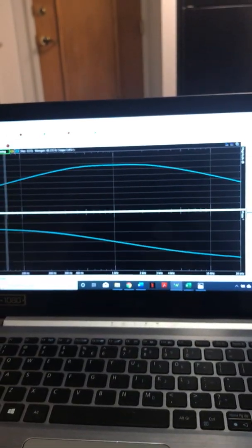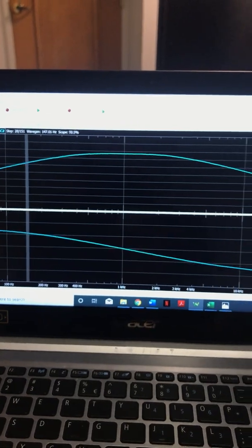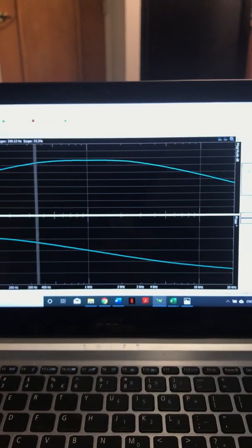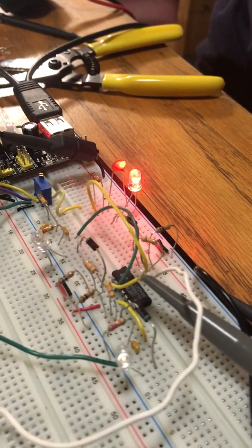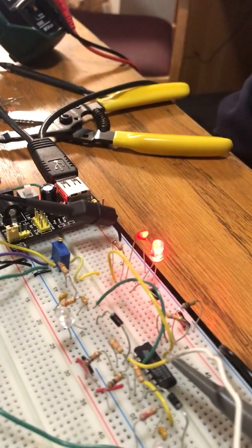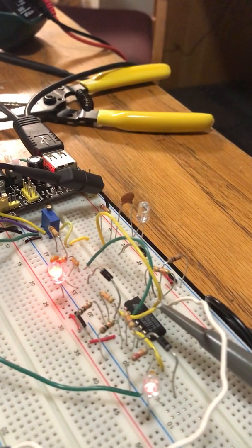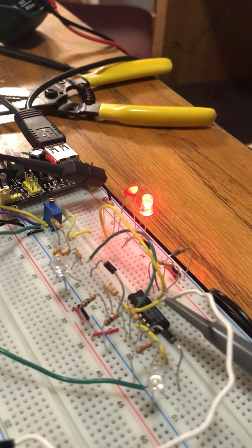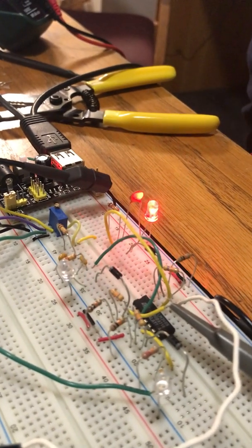So the band pass is made up of a low pass filter and a high pass filter, and we can actually calculate the center frequency of the band pass filter by taking the square root of the multiplied frequencies of the low pass and the high pass. Well, not the center frequencies. The three decibel cutoff frequencies are around 750 hertz and 1.25 kilohertz, and right in between that is 1 kilohertz.